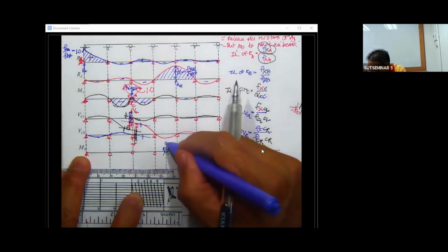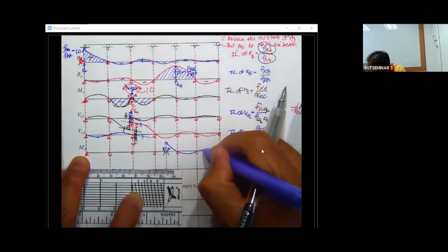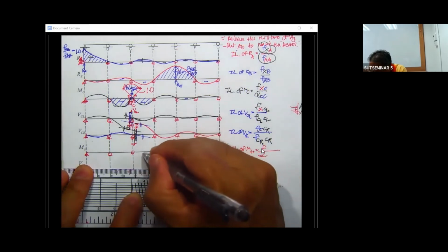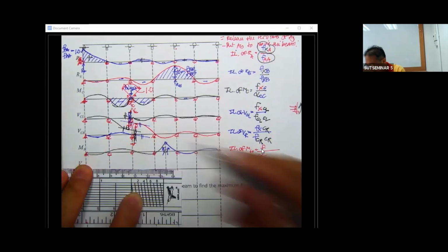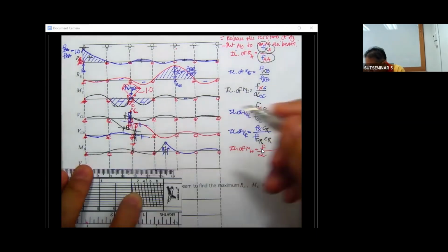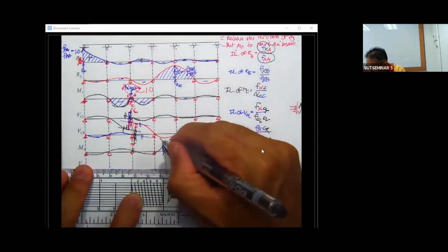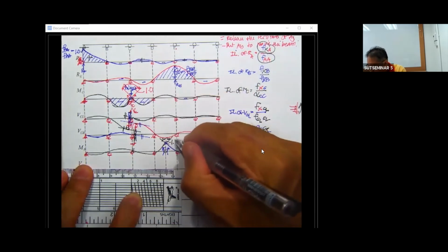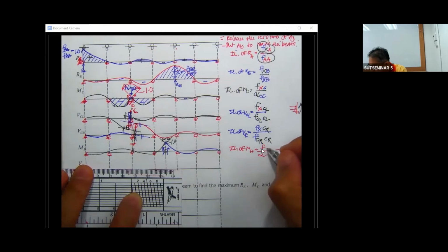But by doing this, the deflection is going to have a shape something like this. The angle here is required to be, as before, 1.0, and this one is going to be the deflection at any point X when the force is applied at H. And the angle here is alpha sub HH.